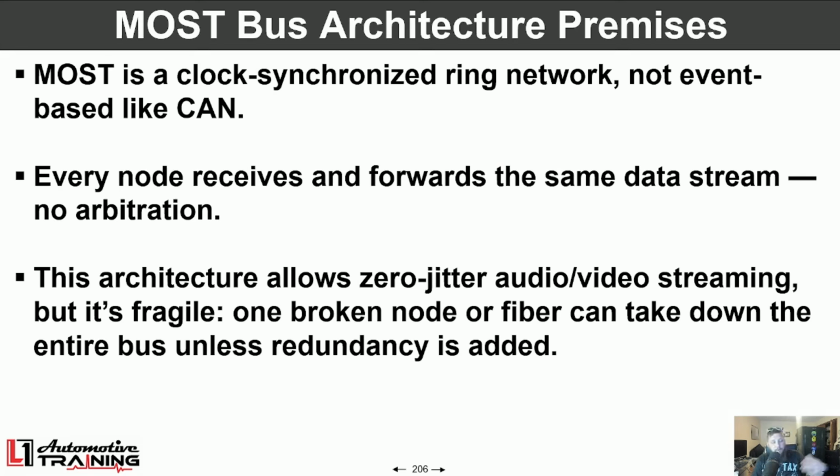Now, like I spoke about this before, it's a clock synchronized ring, so there's no event base. Each module forwards all of the data, puts its piece on there, talks, and it just continually goes around. Whatever module is the master node on the network is going to set that synchronization signal, like the rate at which it talks.